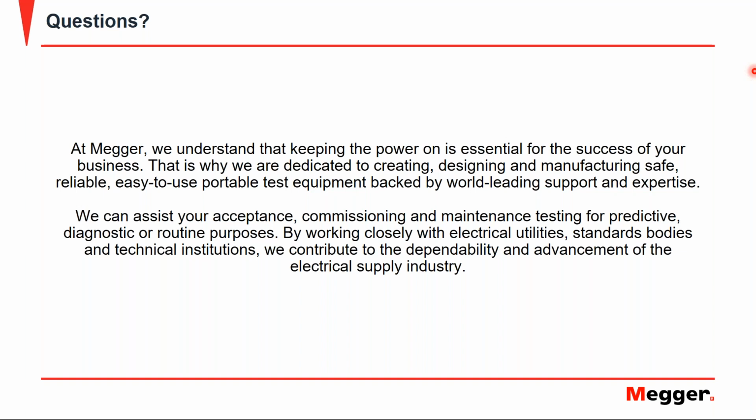There are going to be more alternate paths to produce partial discharge, it's going to influence the partial discharge measurements you're getting, and it's going to be extremely difficult to have repeatable measurements whenever you're doing future testing on that cable.